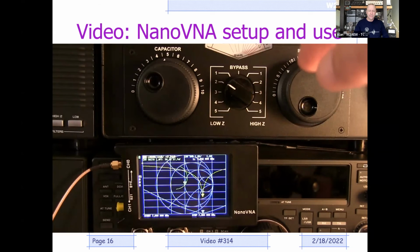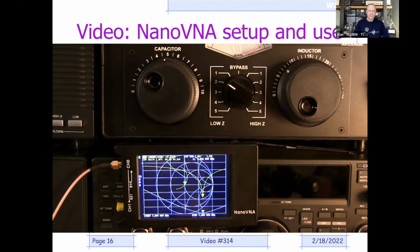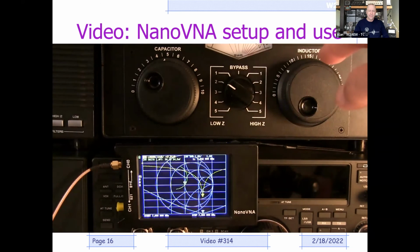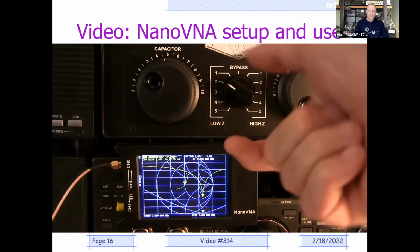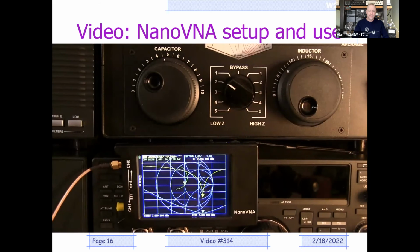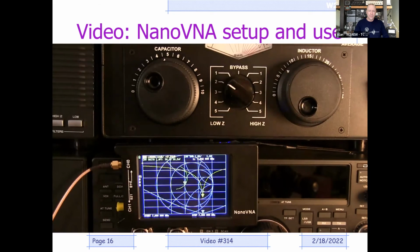And this is where I find it handy to have the Smith chart shown on the VNA, because you can actually see how the controls on the antenna tuner are going to twist and roll the trace on the Smith chart, and it gives you a little bit better intuitive feel about which way to tune the various controls.